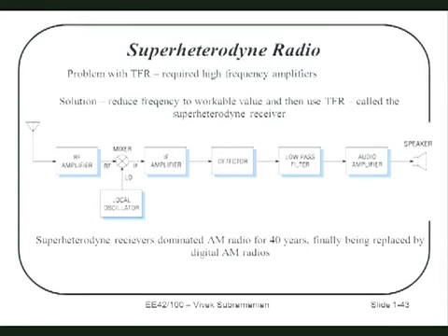So what they did was they came up with a superheterodyne radio, where no matter what frequency we had coming in, which we could tune to 740 or 860 or what have you, we would then shift it to a known frequency. And that frequency was actually 455 kilohertz. Then all the rest of our circuits would be really high quality circuits designed to operate at 455. So we would get really high quality sound with really good separation of channels, because we would get rid of all the other spurious stuff because we would shift everything to the right frequency. This was called a superheterodyne receiver. Very widespread. All major receivers were made this way for 50 odd years.